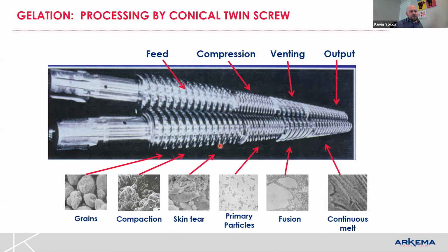If we think about that in the longer case, where we take away from a cross section of the screw and go out to the full screw with the flights, the same process is happening, but now we're conveying the material from the hopper to the die. The process now has to take place along that extruder barrel and essentially do the same thing, except instead of staying in one stationary place, we move along the barrel. So it's the same idea. This is all what we're trying to do with this very simple piece of equipment, the torque rheometer.